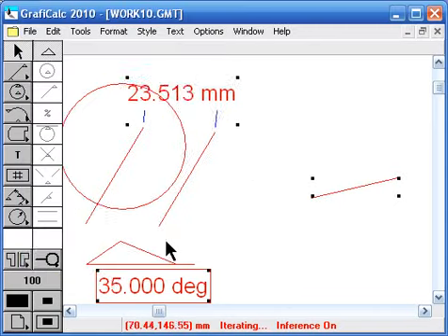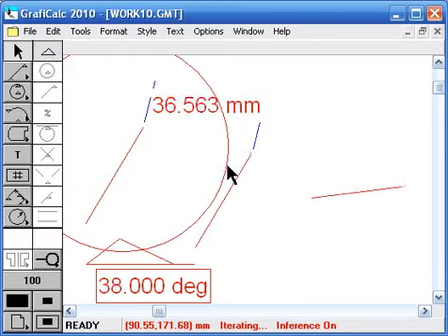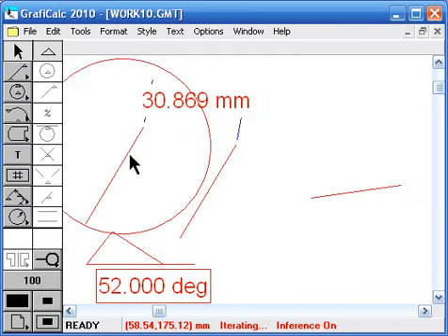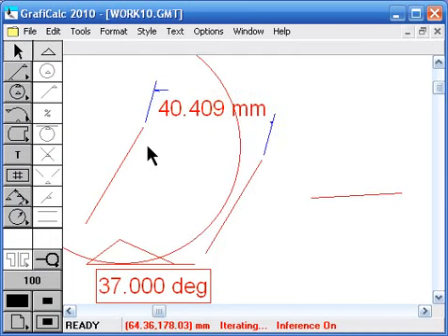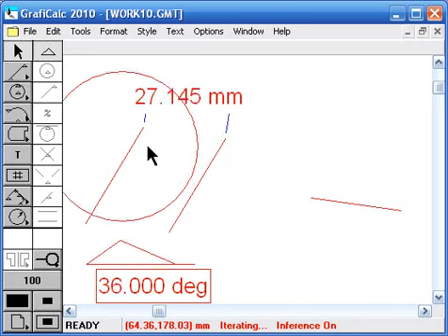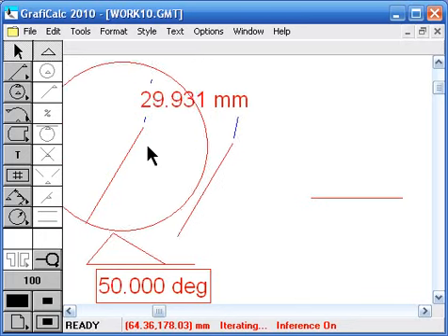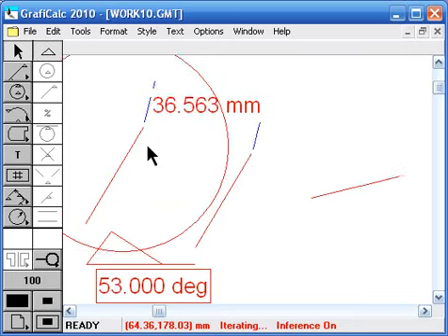So to summarize, value generators are used to control any freedom of any geometry through a range of values, and the value generator can be a straightforward value generator, or it can be programmed using any of the built-in functions that are available in the built-in function library.